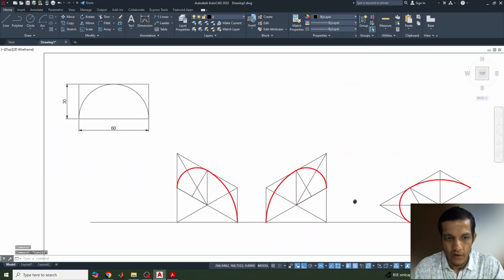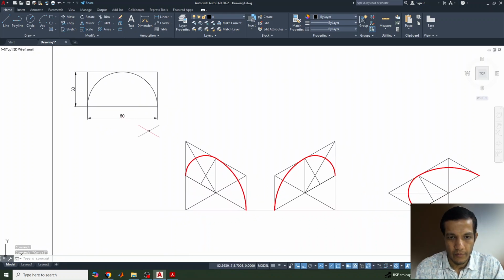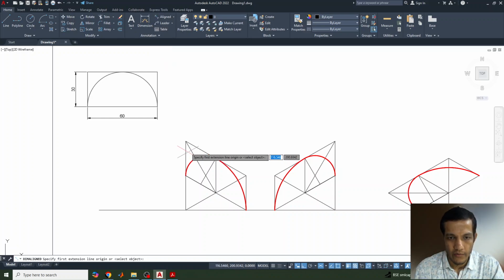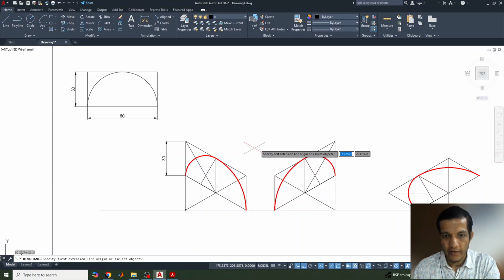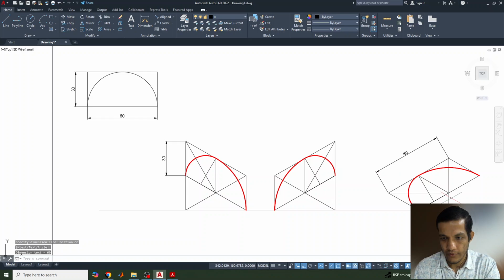So you can see all these things in one plane, we have completed everything. Now we need to give all these dimensions. Dimensions we can give in aligned dimensions. Just click it here. See, we have taken the iso top, but we are giving in the iso right. That is not correct. So we'll go for here. Again, I'll just select this one. Okay, and you can change it to iso left and select this dimension from here to, or the dimension we can give easily, we know very well how to give it.